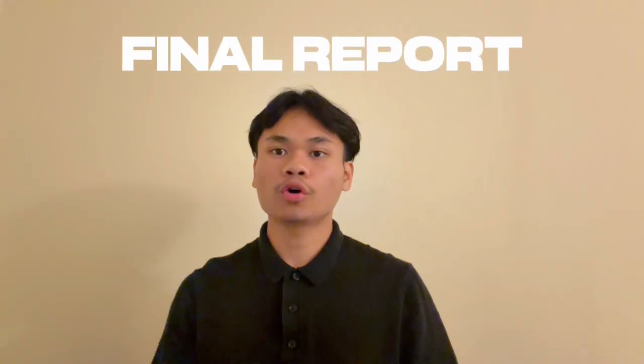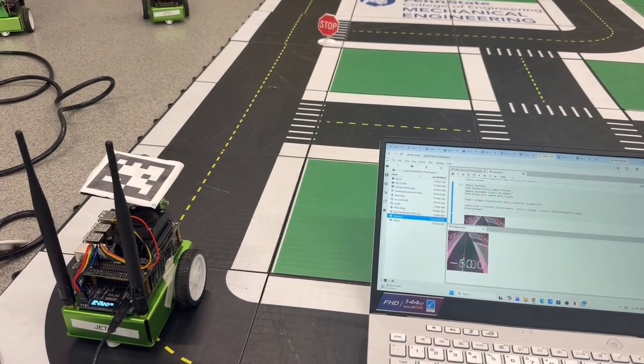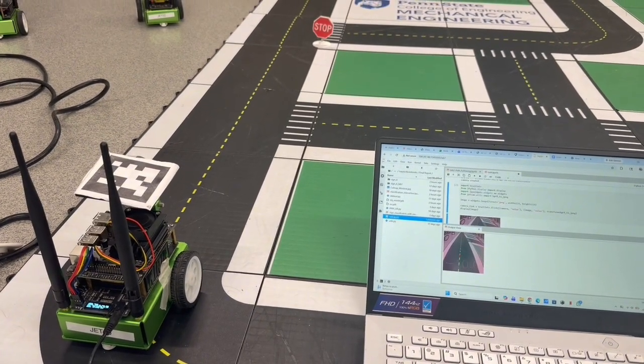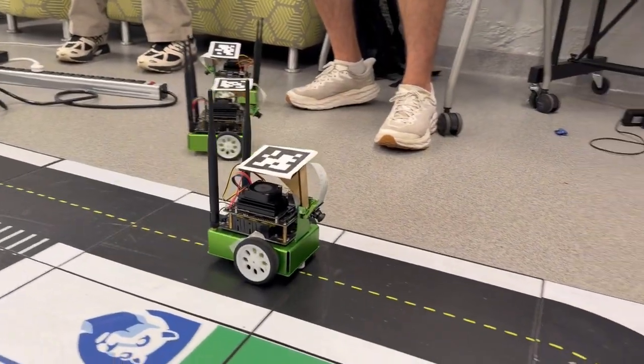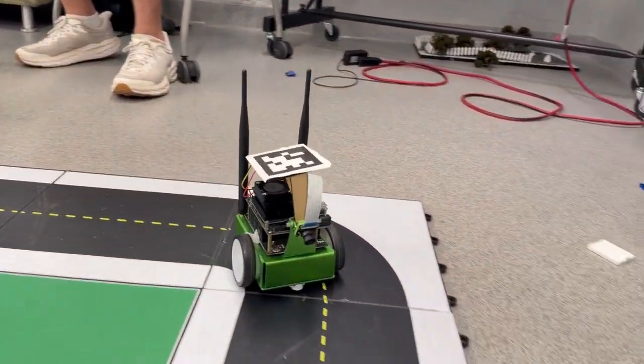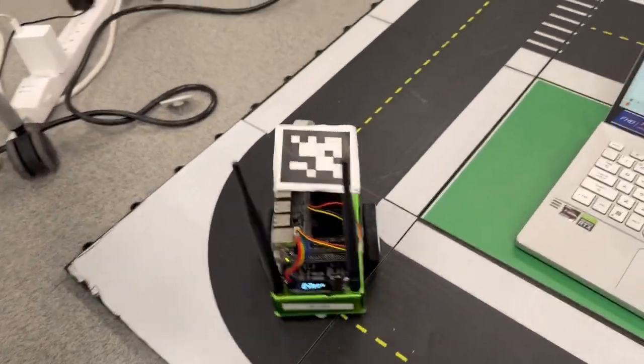In this lab, we combine three parts from the previous labs: path following, sign recognition, and kinematics. First, for path following, we use the sample code from Lab 2 and modify it so the JetBot can follow the line smoothly. It can move along both straight and curved paths, and as long as there is a visible line on the road, the JetBot will follow it regardless of the direction.